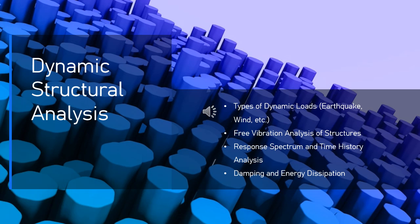Rayleigh damping assumes that the damping matrix C is a linear combination of the mass matrix M and the stiffness matrix K. C equals alpha M plus beta K, where C is the damping matrix, alpha and beta are constants that control the relative contribution of mass and stiffness to the damping behavior, M is the mass matrix, and K is the stiffness matrix.